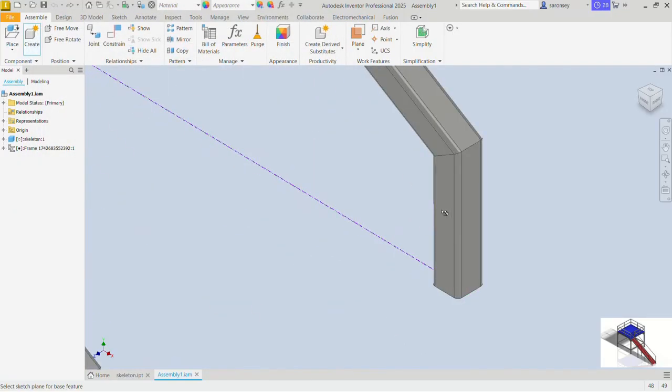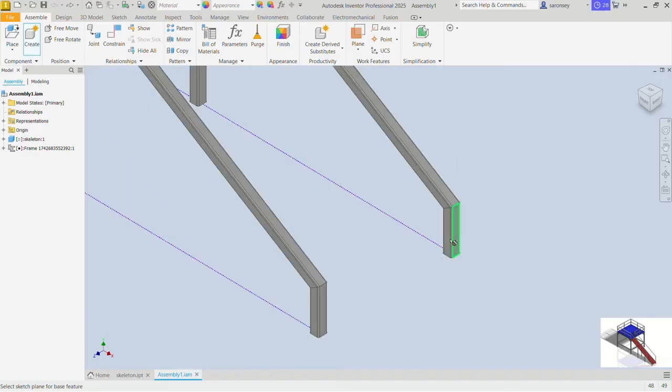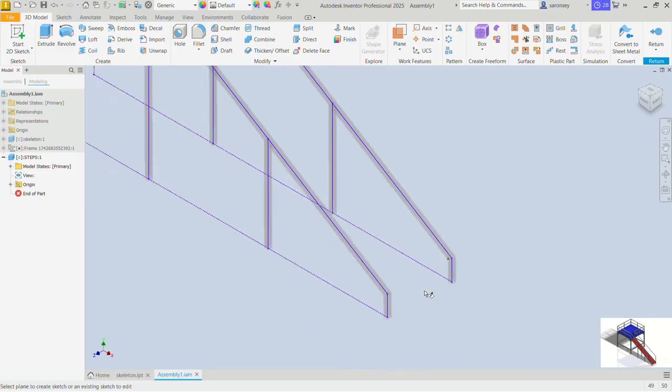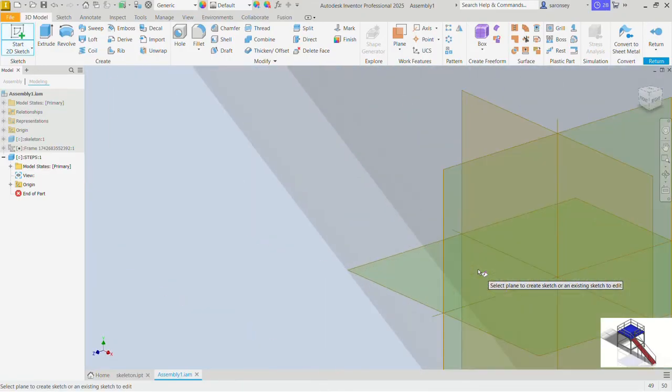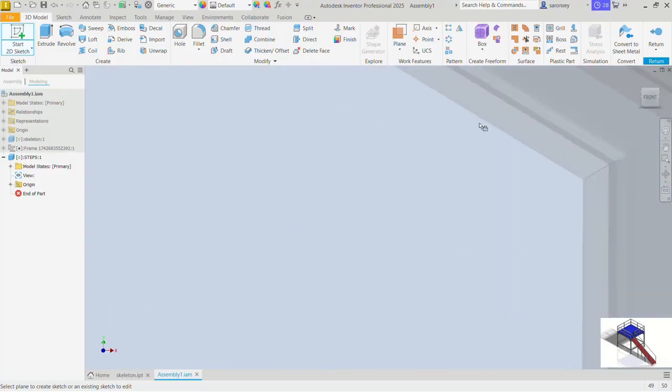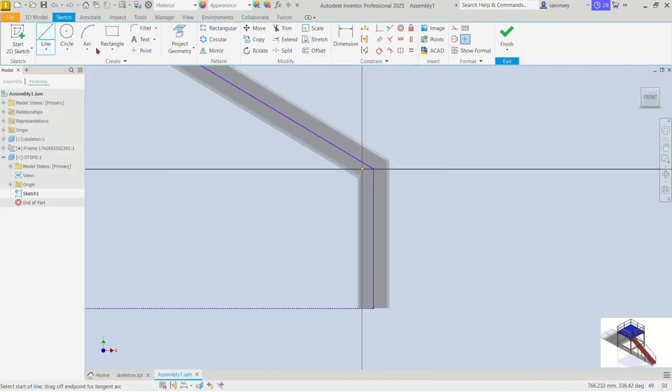Now we will select the face we want to create this sketch, which is going to be this face. You now right click. Let's choose new sketch. Let me zoom in and pick the XY plane, which is this very one, so I can create my sketch there. Now we will pick the line command and draw this profile here. The length of this line is going to be 6. We would enter that. We'll move up perpendicular to that to a distance of 80. Let's enter that. Let's move perpendicular to that horizontally to a distance of 212.